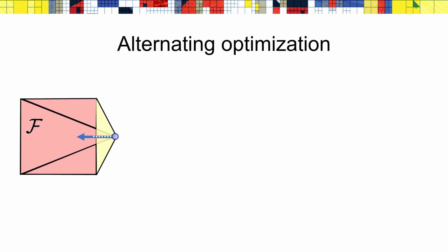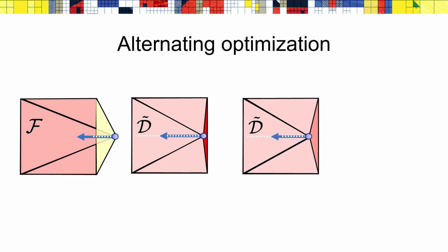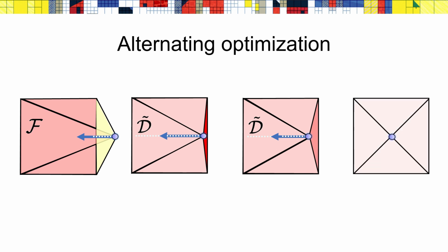So we start with a fixer stage in which we optimize the invalid penalty F to repair inversions and collapsed elements. After a certain number of iterations, we switch to minimization of the modified rotation invariant distortion d tilde. When all invalid elements are fixed, further processing is devoted solely to d tilde, which at that stage is equal to the original energy d, and the process is terminated after convergence of all measures. Here, dashed lines depict the interval of line search that we have modified for our needs. Please see the paper for details on our enhanced line search and on ABCD convergence criteria.